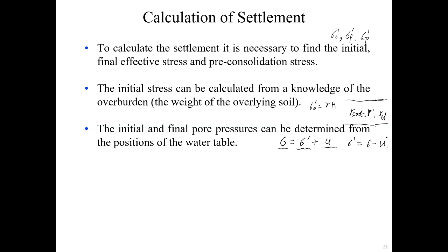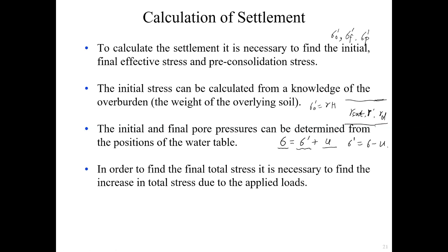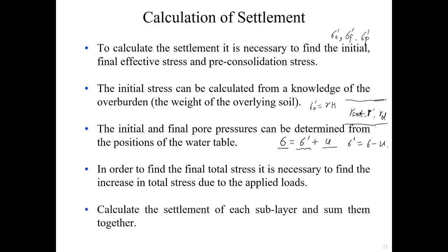So that's what it means here. And we also need to find the increase in total stress due to the applied load to work out the final total stress. And finally, we calculate the settlement of each sublayer due to previous formulas and add them together.